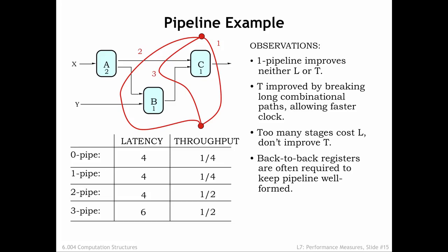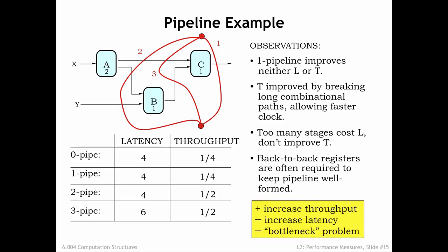Note that the signal connection between the A and C module now has 2 back-to-back pipelining registers. Nothing wrong with that. It often happens when we pipeline a circuit where the input-output paths are of different lengths. So our pipelining strategy will be to pipeline implementations with increasing throughput, usually at the cost of increased latency. Sometimes we get lucky and the delays of each pipeline stage are perfectly balanced, in which case the latency will not increase. Note that a pipelined circuit will never have a smaller latency than the unpipelined circuit.